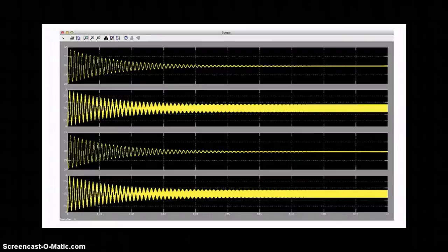Now, as we all know, VC is the sum of VL plus VG, and this VC will come directly on the output load with a minor resistance drop. Since the input given is 12 volts, we can easily see that the output voltage is settling at 30 volts.